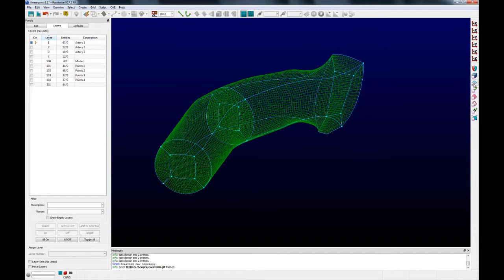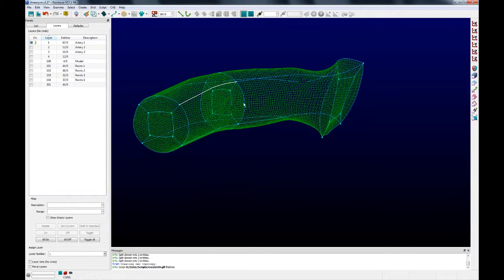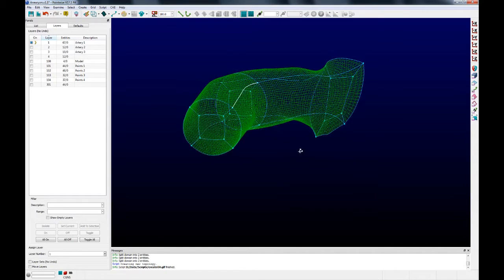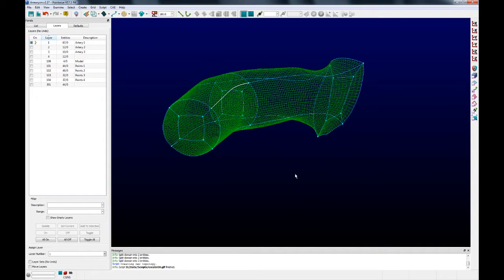To do that, we're going to be using the copy and paste command in Pointwise. So we could draw curves manually, but because of the twists and turns, it's going to be a lot easier to just copy and paste. That way the connector already has the natural curvature that we want. It's also by default dimensionally balanced, since we're going to eventually want to balance this connector with whatever we place in between these points there.